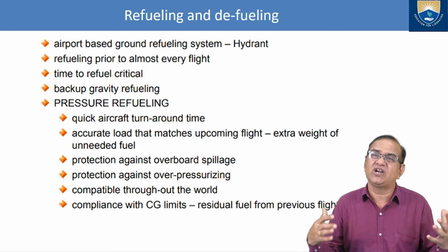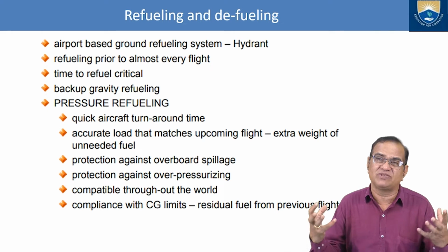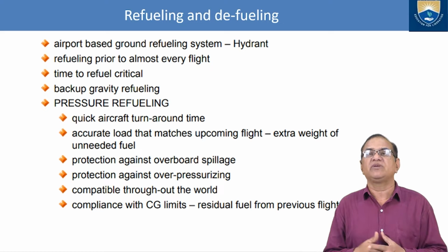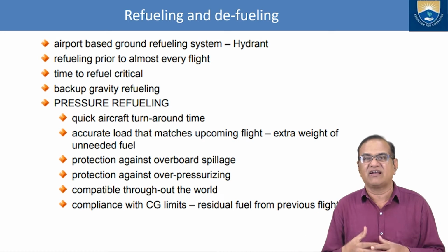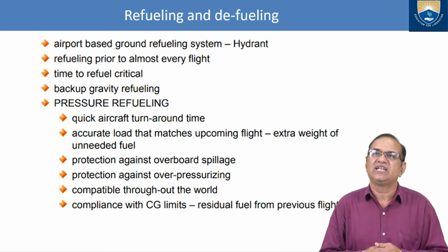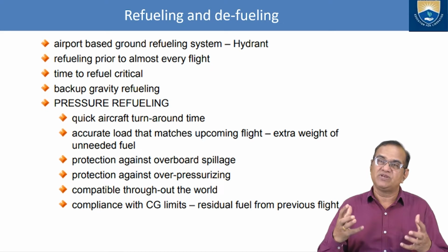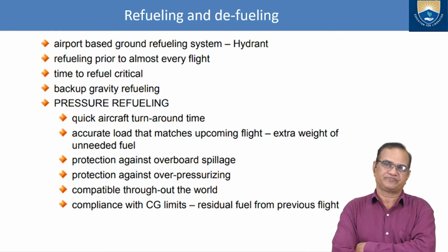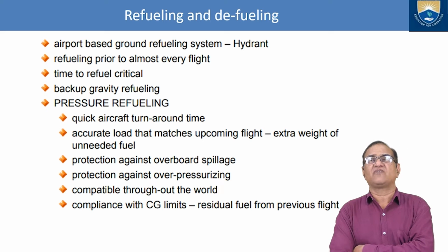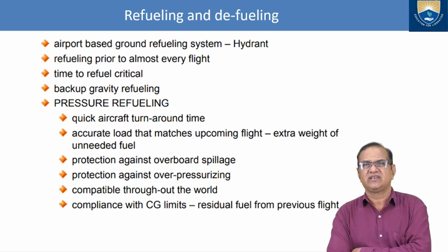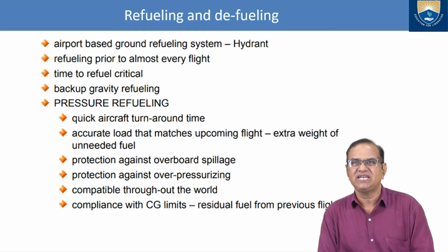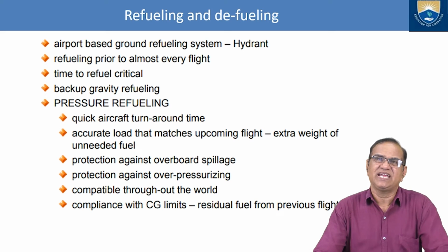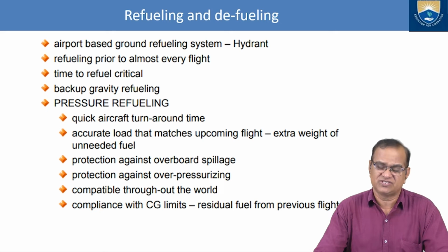And in case we are doing some servicing, or we need to reduce the weight of the aircraft on the ground for jacking up the aircraft, we don't need the fuel to be there. Or during maintenance, if we are doing welding on the aircraft, we have to jettison or remove the fuel. That is called defueling. Defueling is removing fuel from the aircraft tank to the outside. So these 2 operations are very important and we should make sure that proper precautions are taken.